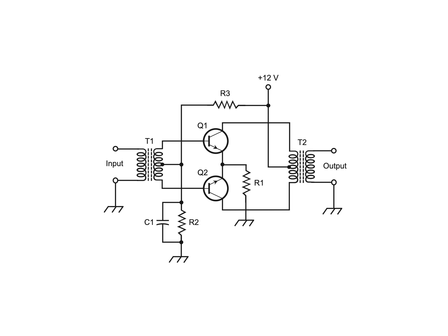In the push-pull circuit, the input signal goes through T1 and appears across its secondary. The details of the ensuing process get rather complicated, involving wave phase and transistor characteristic technical matters that go beyond the scope of this course. Basically, Q1 handles half of the signal cycle and Q2 handles the other half, as the audio input AC flows alternately up and down through the secondary winding of T1. Transformer T2 combines the two amplified cycle halves back into a complete AC audio wave that's stronger than the wave that came in through T1, thanks to the transistors.